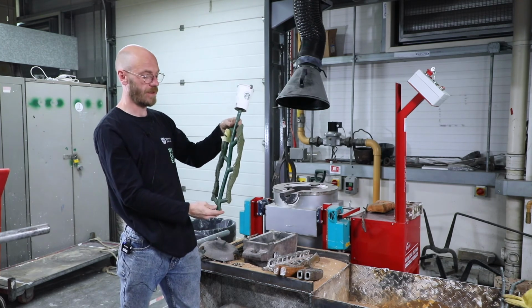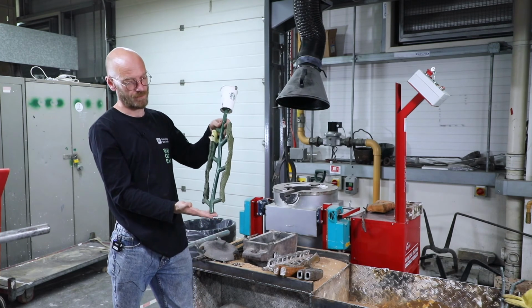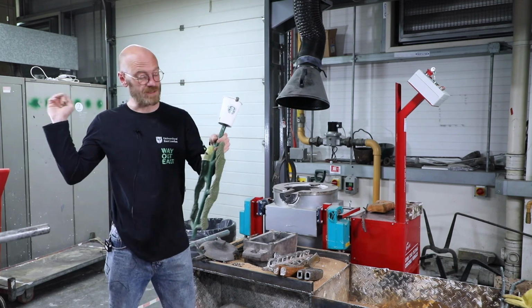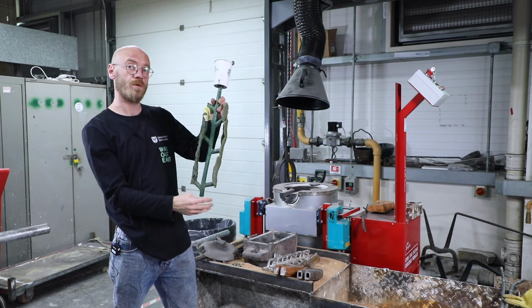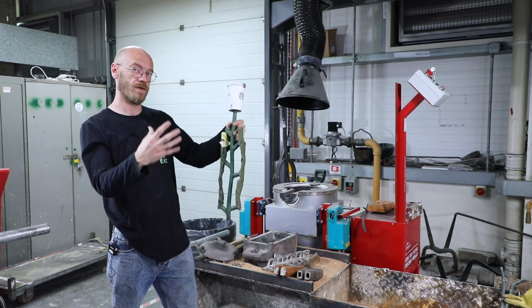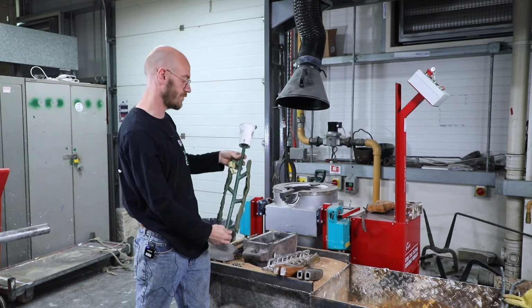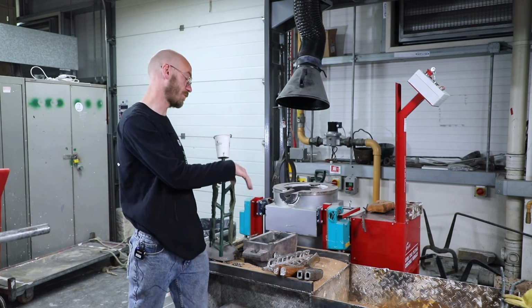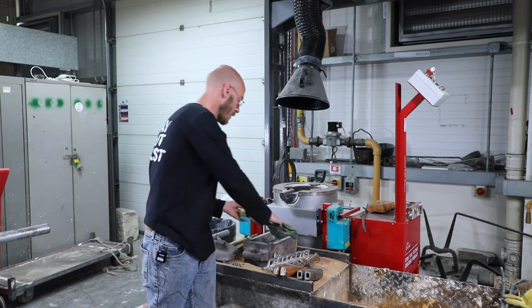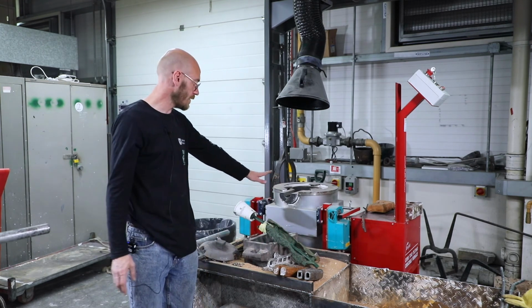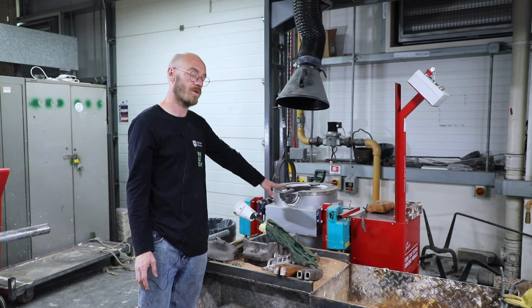And then from here they'd create a mould with a plaster mix, and then it goes into the kiln, it burns away all the wax, and then you're left with this plaster mould and your relief of your object, and the runners and risers are inside. And at that point, you would bring it over to here, to the bronze foundry.